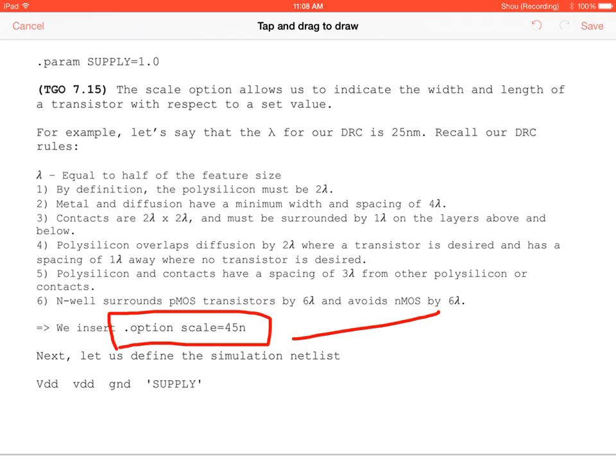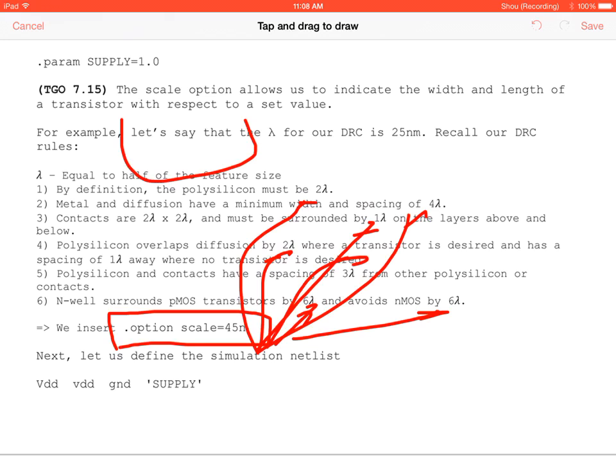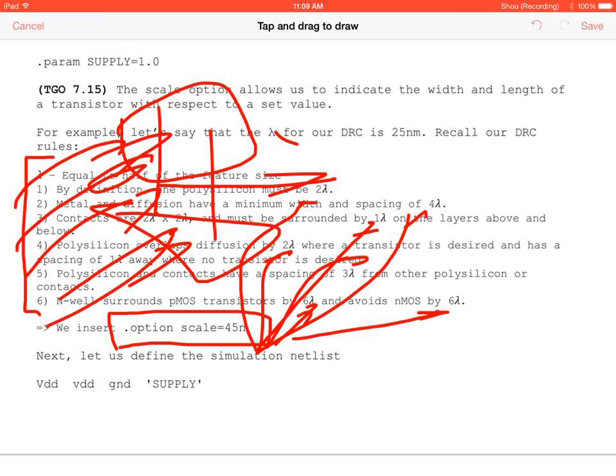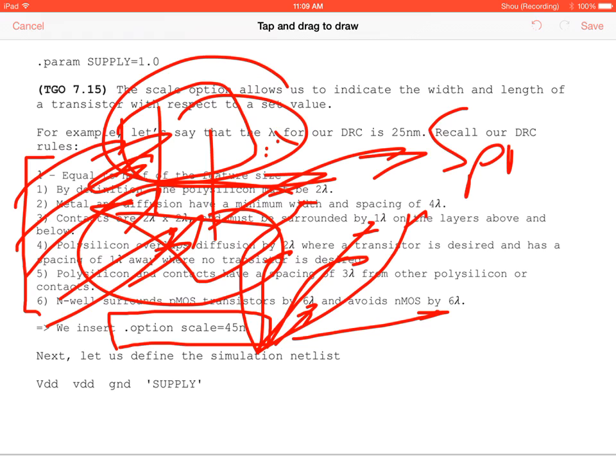And the reason we do this is because this is how everything's met. So the way it's going to work when you want to actually compile your layout, you're going to initially start with your polygons, right? So you have some sort of input and output. The first thing it's going to do is check these rules to make sure you've laid it out properly. And then based on this, it's going to convert it to SPICE. It's actually going to generate a SPICE file.